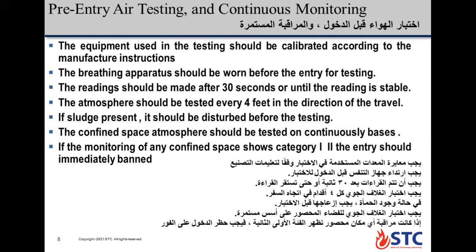The breathing apparatus should be worn before the entry for testing. The readings should be made after 3 seconds or until the reading is stable.